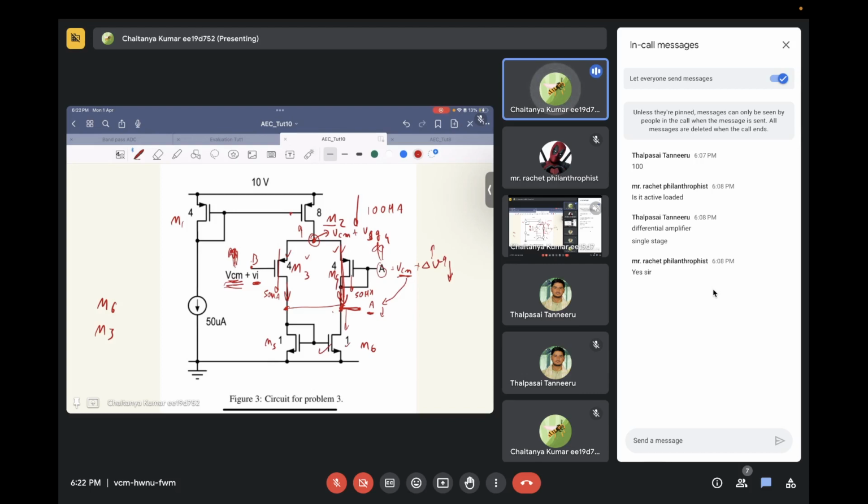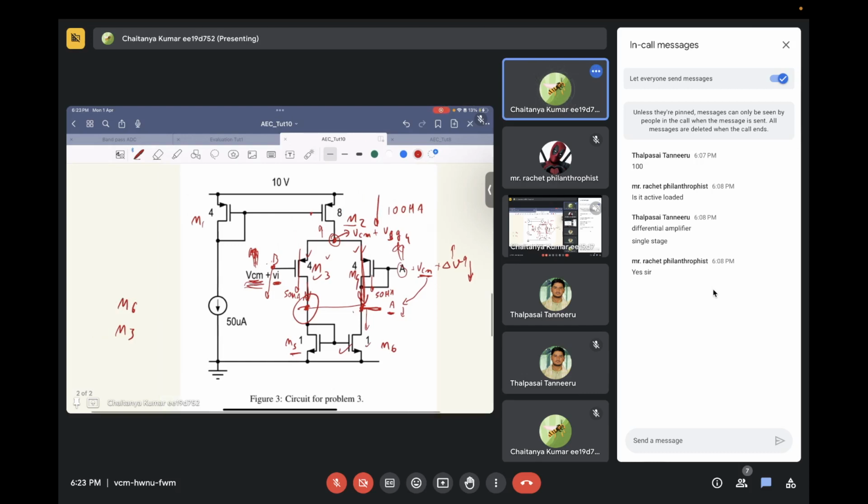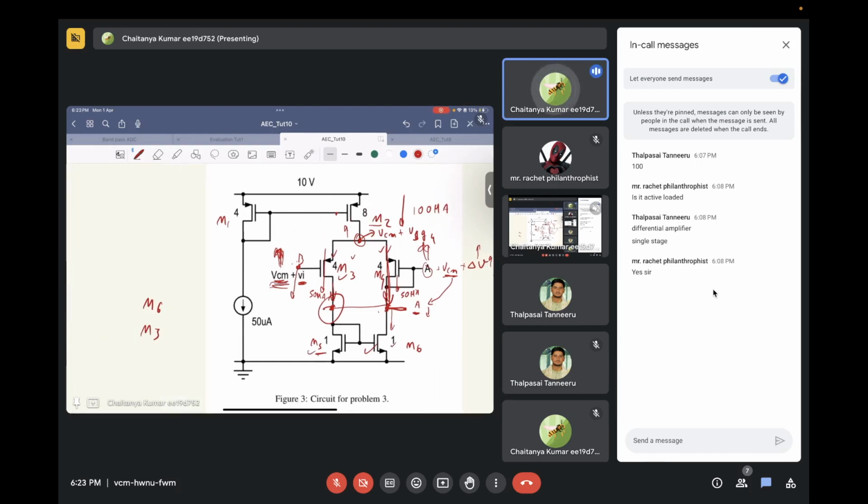The other possibility is that the drain of transistor M3 is fixed at VGS of transistor M5. Since this node is fixed and the gate of transistor M6 keeps on reducing, transistor M3 might go out of saturation if VCM goes one VT below the VGS of transistor M5.